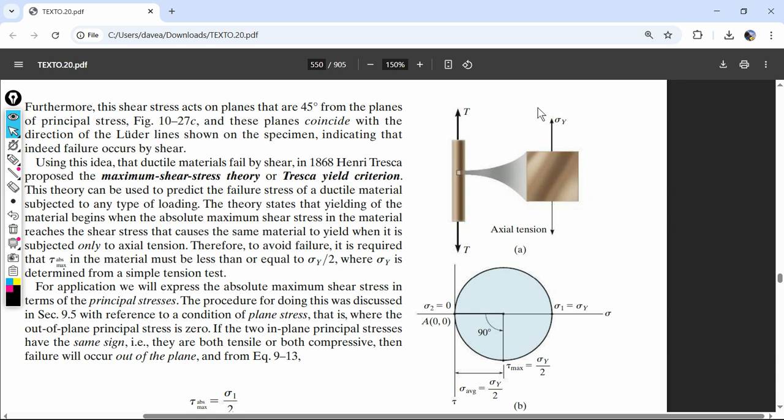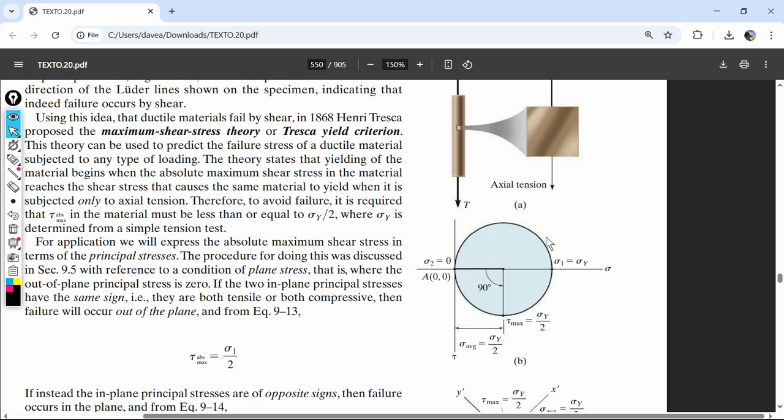The other number is negative. I'm pretty new to the Mohr circle, but I just know from this, you draw your circle where this is always your first principal. Even if this circle is shifted over here, this principal stress could be 0, and then your max compression would be over there.